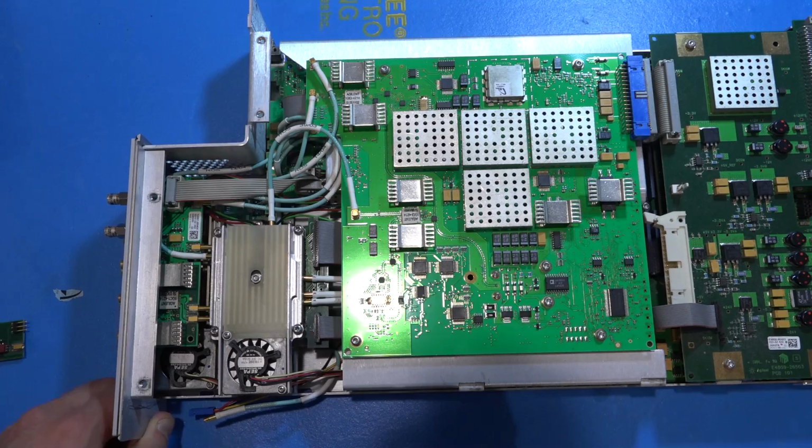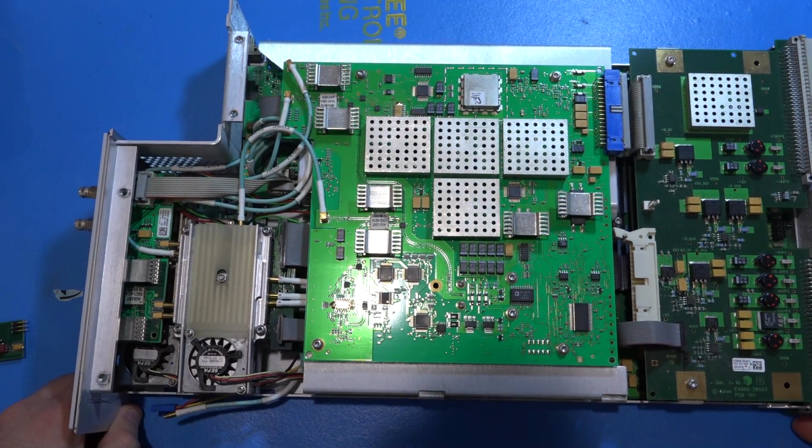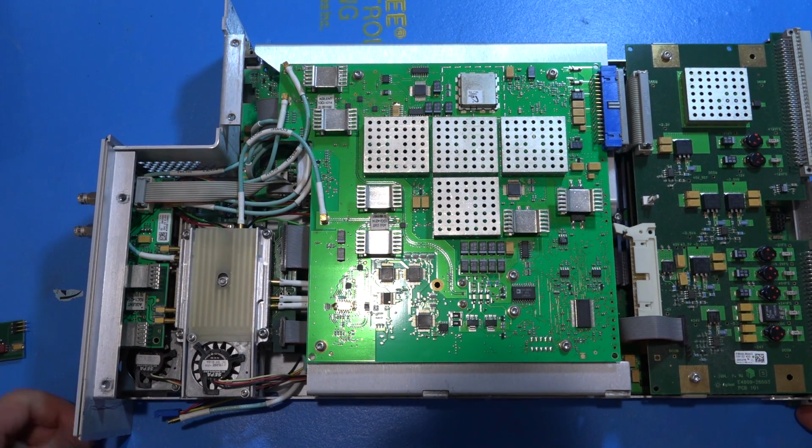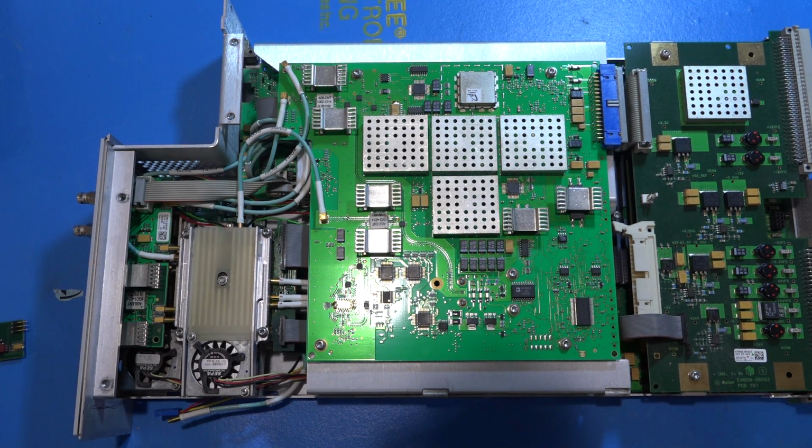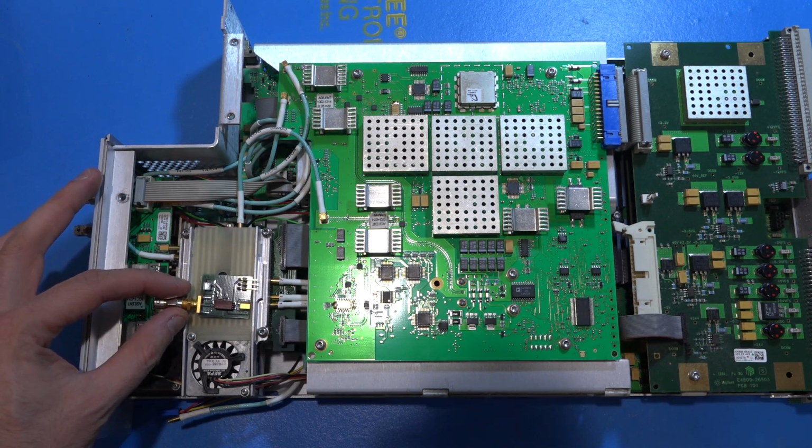These things are quite power hungry. These are basically very fast slew rate, I would imagine quasi-linear output drivers which drive into 50 ohm differential, and this is what you would expect from a backplane driver. Nowadays it's so much more integrated by about a factor of 1,000, so it's really quite incredible. And of course at Bell Labs we built these kinds of devices too. So now what do I do with this? Well, let's take a look and see what's going on here on this module.